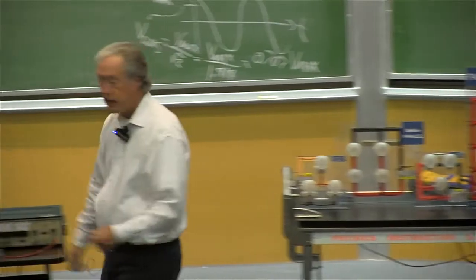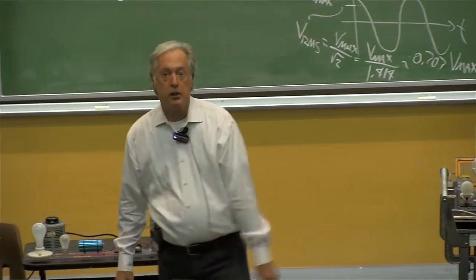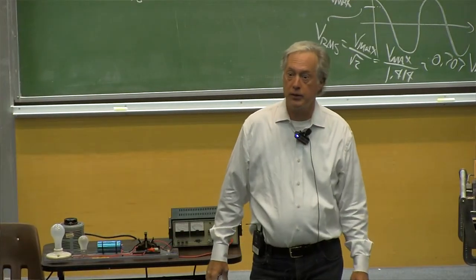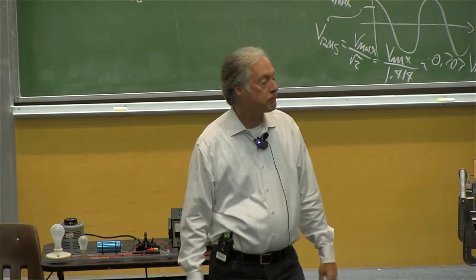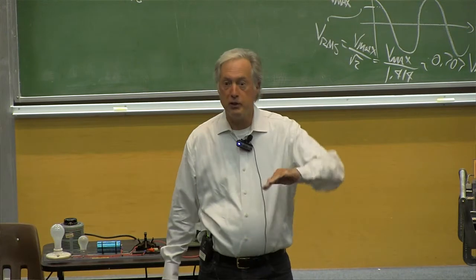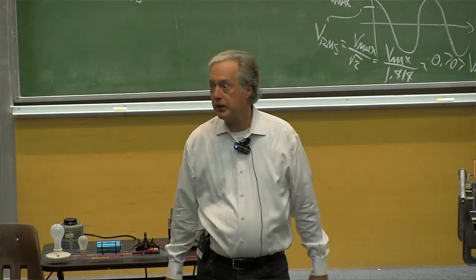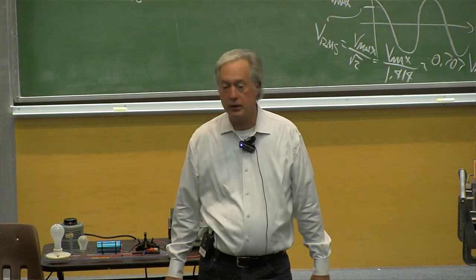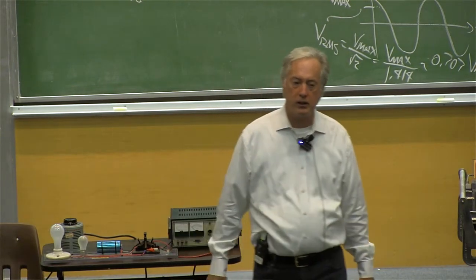When you go over and stick something in the wall, the RMS voltage is typically about 120 volts in the US. 120 volts at 60 cycles per second. That means the V max at the wall is about 165, 170 volts typically. Higher than the 120 you're talking about.